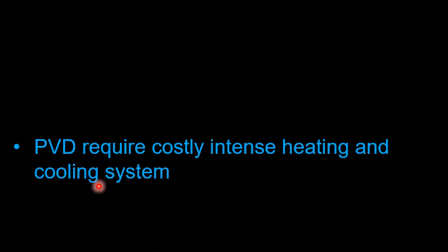Whereas the interesting fact to notice here is that for a CVD system, though different kinds of cooling systems are used, like water, you don't need a mandatory cooling system for cooling the precursor material and substrate. But in the physical vapor deposition process, you need a cooling system to cool the precursor or source material. So the PVD process is more costly in terms of instrumentation for bombarding the source material and due to the cooling system which is used in PVD systems.